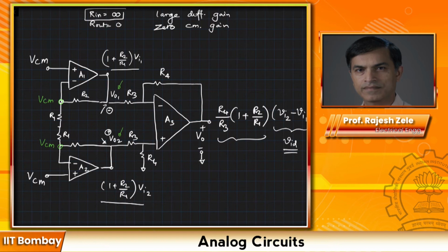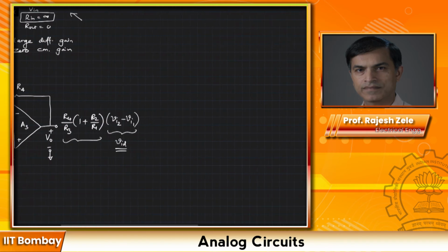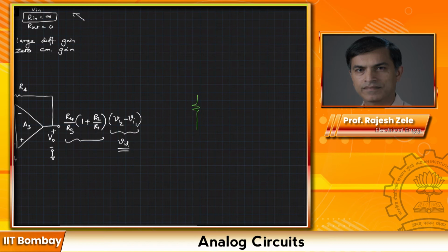What will happen is the following. If you look at this particular part of the circuit, the two resistors connected together, R1 and R1, I'm going to draw them separately over here on the side. So you have one resistor and the other resistor, R1 and R1, and on each side of the resistors we have VCM and VCM. The VCM could be moving around.